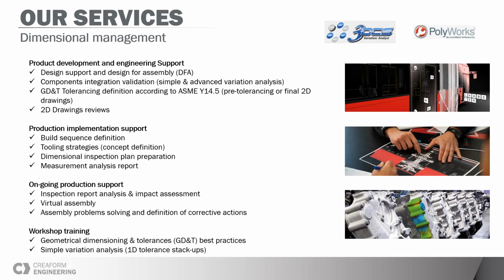You might want to analyze the gap and flushness on the hood when it closes. You want to make sure your gap is constant and that it's flush with the fenders. This is a 3-dimensional analysis, so it's not as simple as what we've shown today, but we have tools. When you get into more complicated stuff, we could do a demo in the future of how 3DCS works. What it does is you can take all your components, put all your tolerances on them in the 3D model, and then it stacks up all these possible variations.